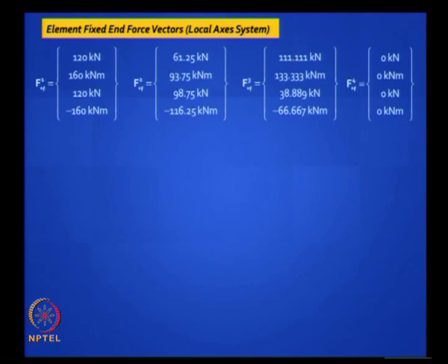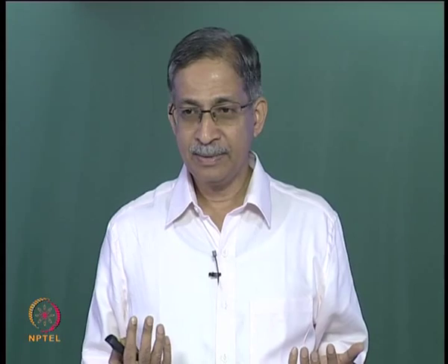You have got these fixed end forces. You have got them in the local axis system. So now you have to link it to the global axis system. How do you do that? Pre-multiply all these vectors with Ti transpose, and Ti is identity. Ti transpose also identity. So you will get back these vectors, but along with them you get an additional linking coordinate system. You just copy down those vectors and add on those linking coordinates which we discussed in the beginning. Is it clear? This step is clear? Very easy to do. What do you do next?